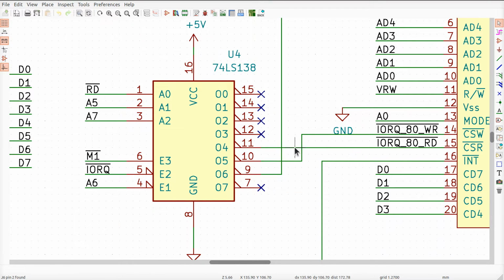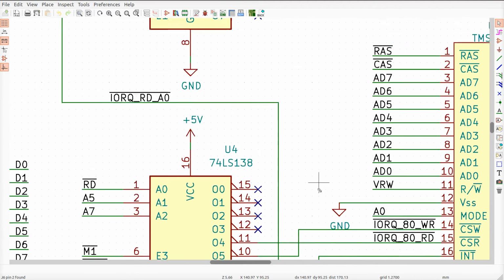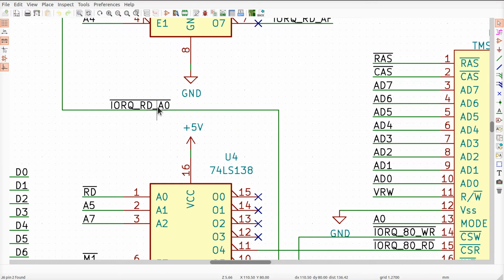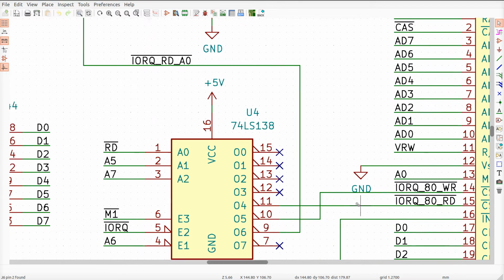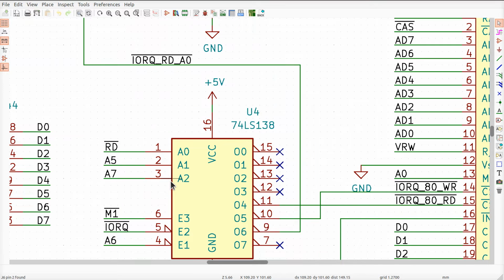Okay, so these two pins here I mark as going valid at port 80 and 81. And this one down here will go valid, if we follow this up here, when I'm addressing values between A0 and BF. Okay, these things go through 80 through 9F in that range. We don't need them all, but in order to decode more pins to reduce the number of addresses that it enables it with, we'd have to play some more games. I just wasted them to simplify the design, okay?